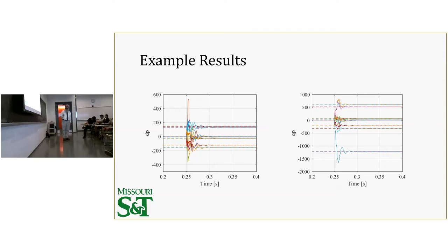you see it has a classic second order type response with some other interesting stuff. And so that characteristic equation captures most of that second order response, but it doesn't capture all of the interactions among the harmonics, because they can oscillate against each other in the estimation process.